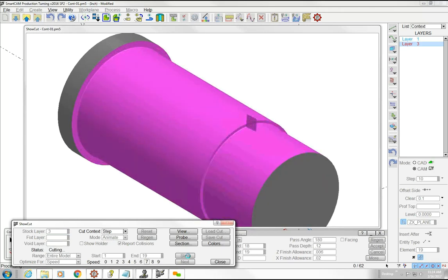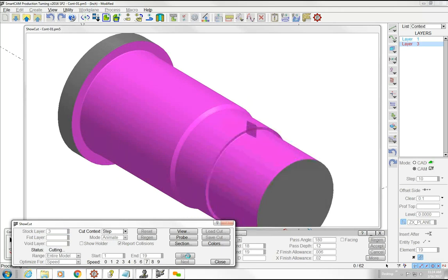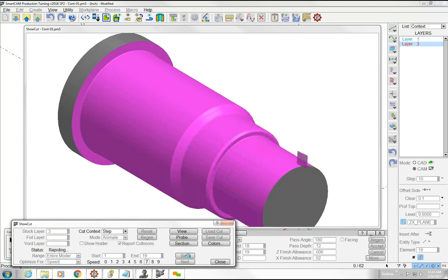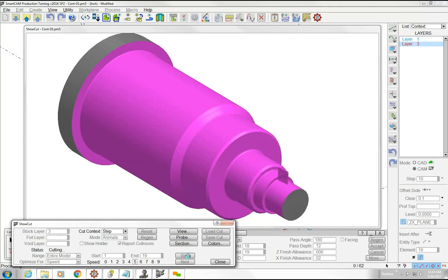By having roughing passes that worked a week ago, you're just creating a new finished profile, and any of the parameters you have in there worked a week ago, they should work today. Everything should be fine. All we changed there was the finished profile, regenerated and then accepted. And we have the new roughing for the new part.